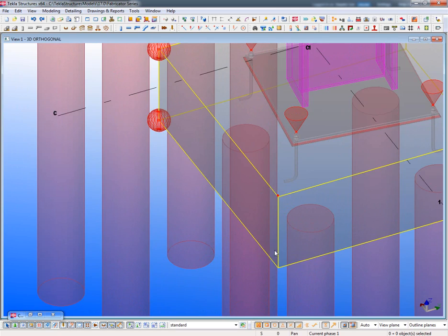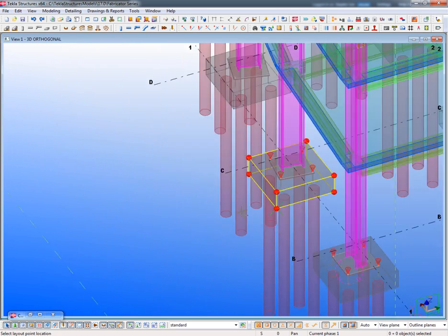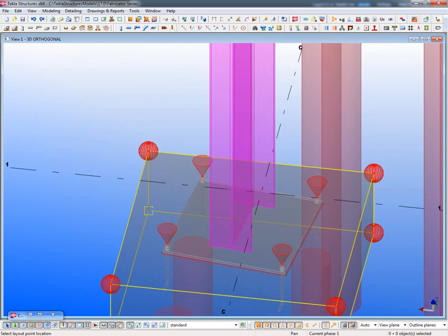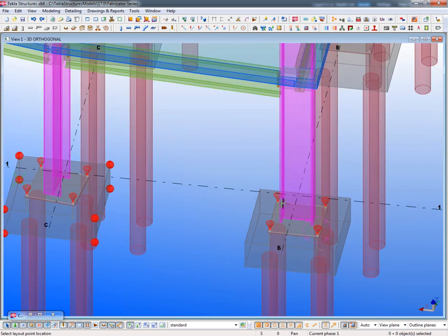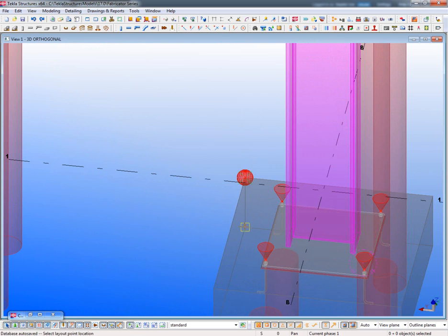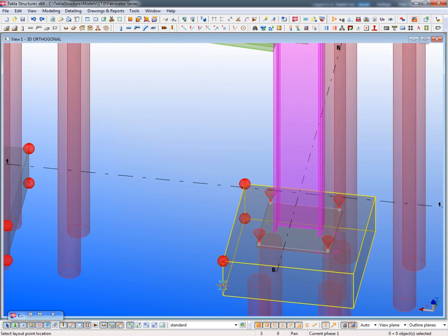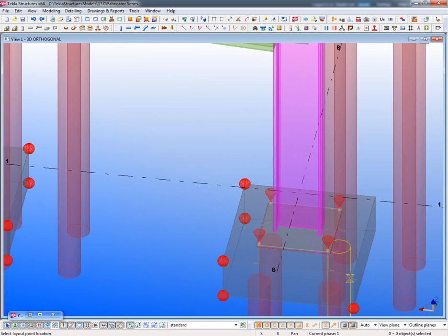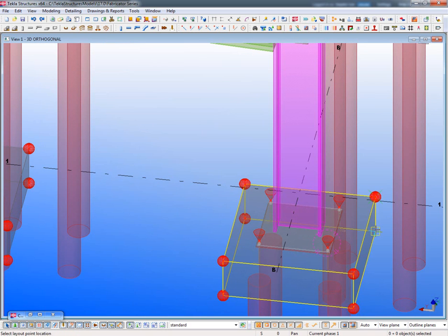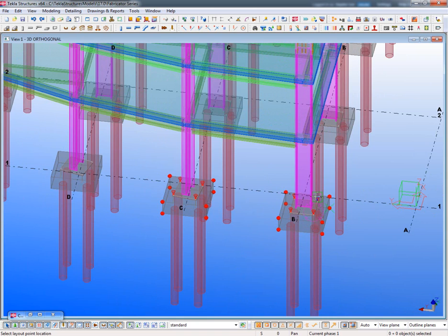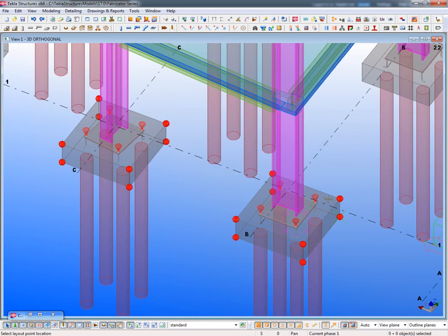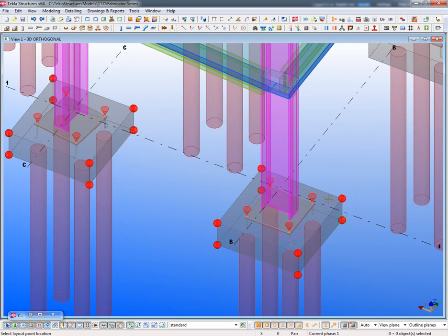What I'm doing is locating the actual points of the slabs here, just to make sure. What we'll be able to do is relay this information out to the field, and then they can snap these points and see the exact layout of where all of this is supposed to be located. But this also works in reverse. Oftentimes you'll send out your anchor bolt plans, they'll pour the concrete and set the anchor bolts, and then maybe a truck runs over them or something.